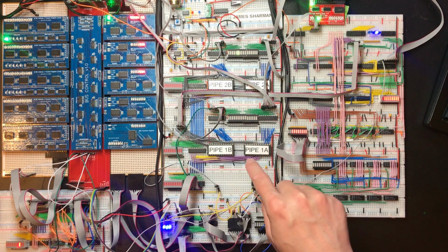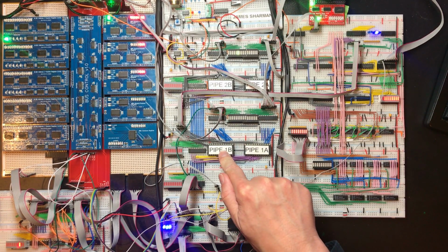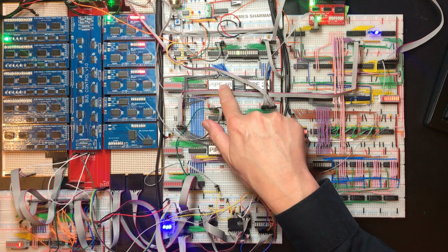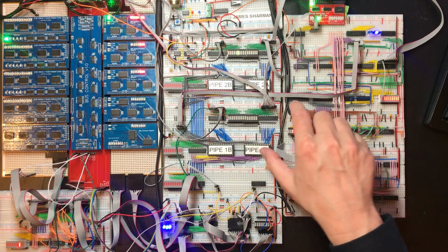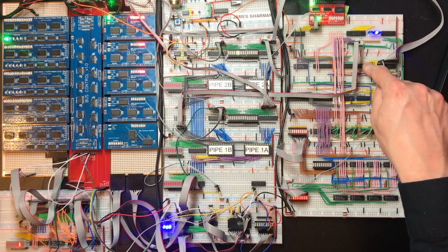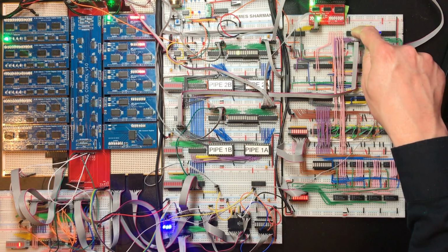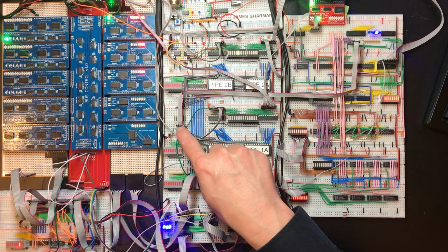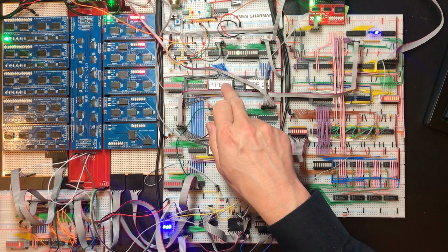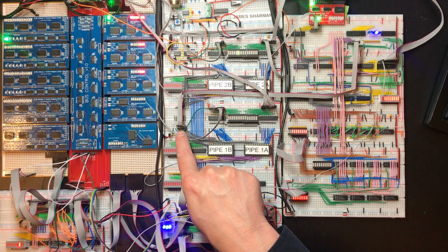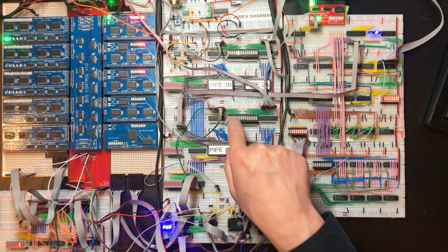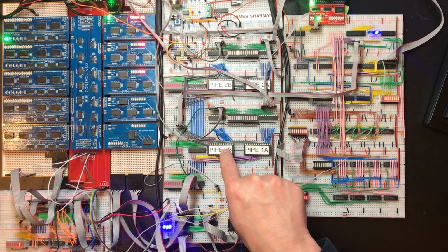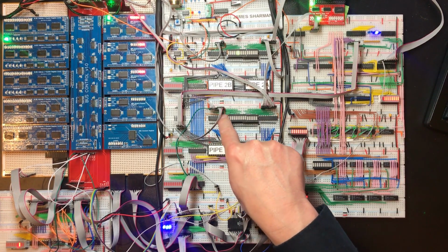Now, an ALU instruction is issued in the first stage and it completes in the second. So most of these flags won't update until a cycle after we issue the instruction, and then the output flags come down to here, and they're not immediately usable by the pipeline because whilst they're used in that cycle to look up the value in the ROM, the outputs from the control ROMs are latched for the next clock cycle.